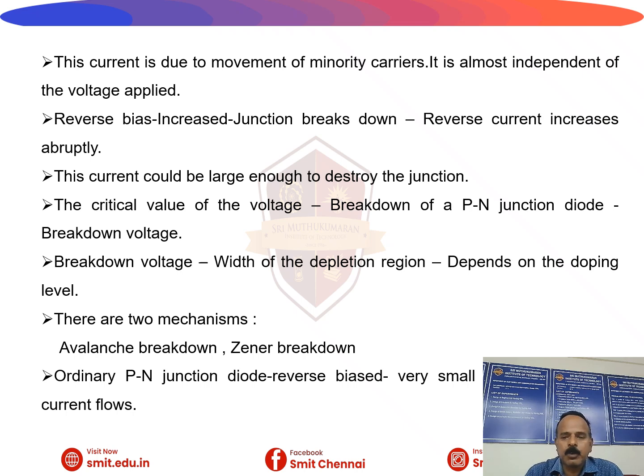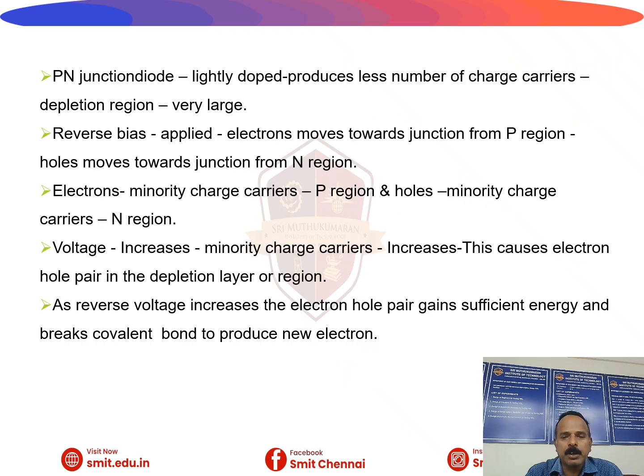Next, we are going to compare the Zener diode versus the ordinary diode, both as a regulator as well as in their characteristics. One of the important applications of the Zener diode is as a voltage regulator. When connected in reverse bias across a load, the Zener diode maintains a constant output voltage equal to its Zener voltage, even if the input voltage or load current varies.